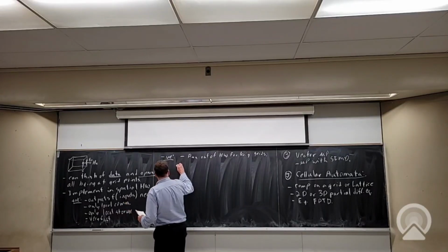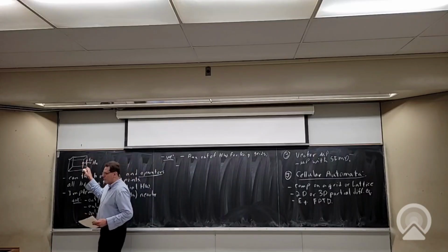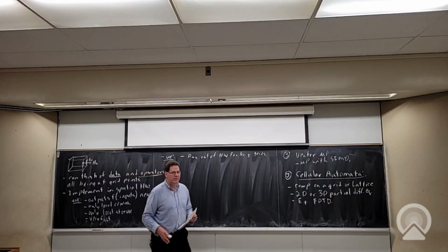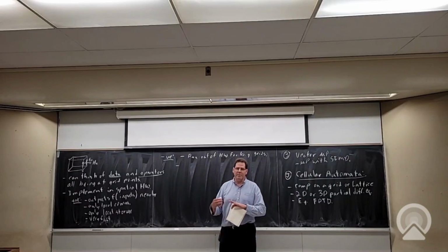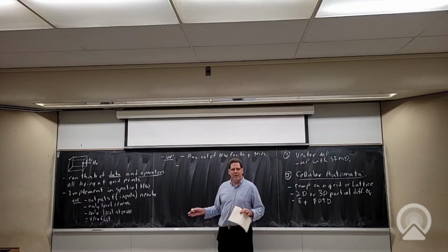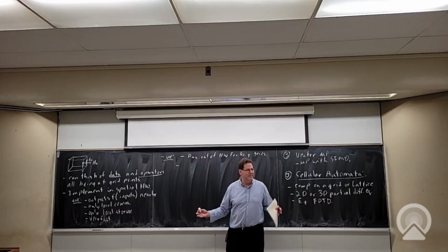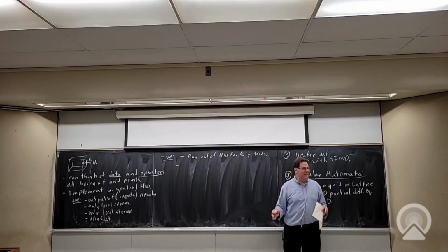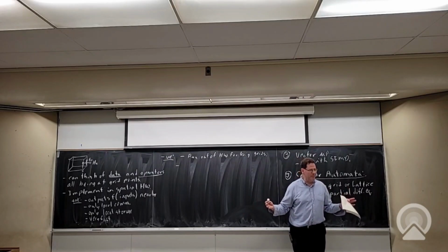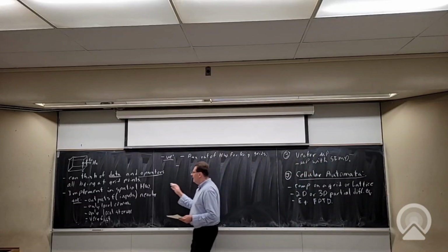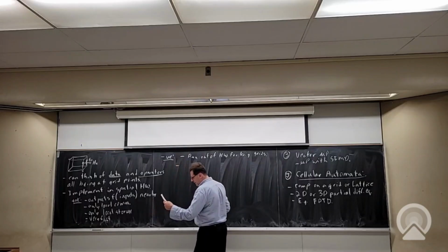So there was a paper where they used this style of hardware to make an FPGA placement engine. They could basically just decide by looking at the local neighborhood of where things were placed what to do next. It was super fast, but in order to solve a placement problem for a 2,000 LUT FPGA, it needed a 1 million LUT FPGA, okay? So there was a problem, right? It could make a really fast placement engine for a small FPGA as long as you had a really big FPGA to implement it. So that's the problem of running out of hardware for these ones.